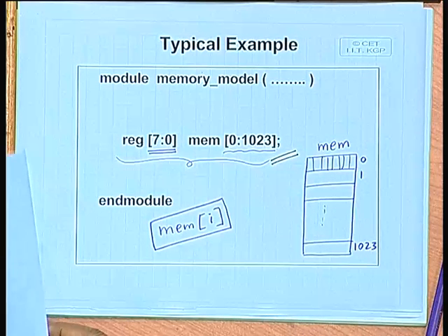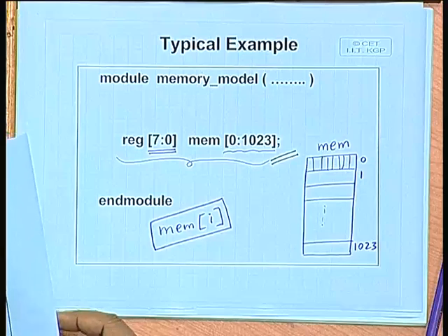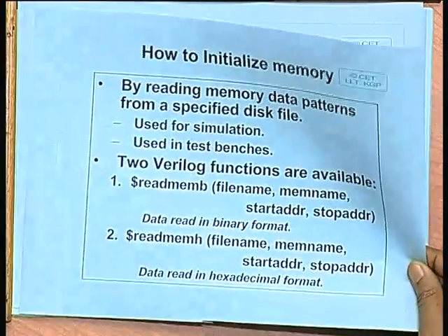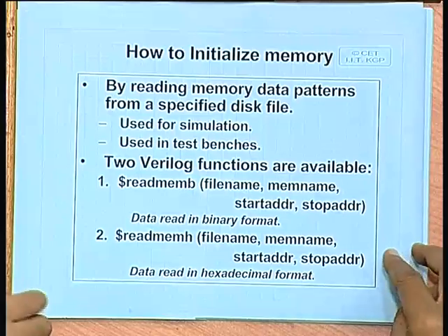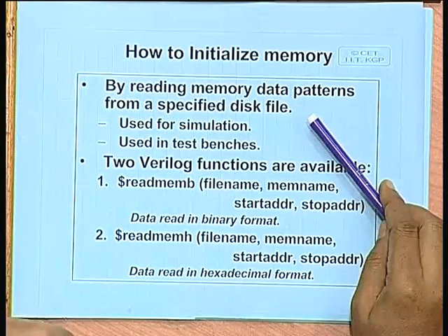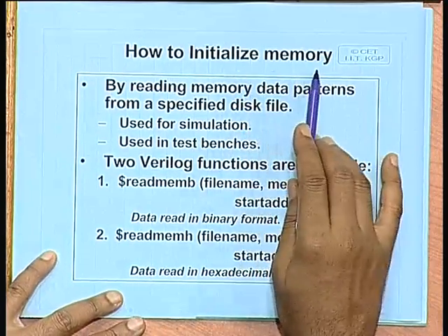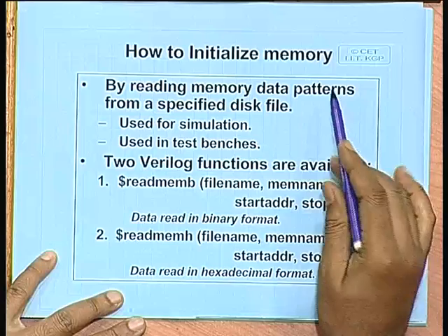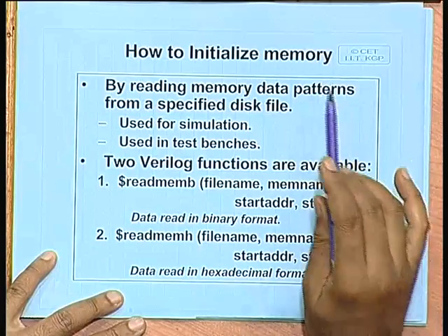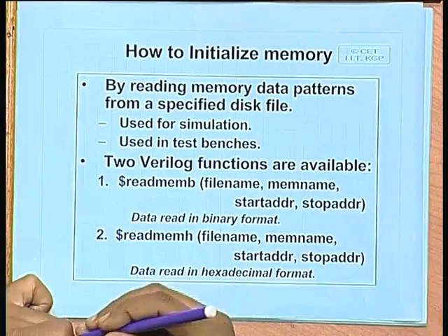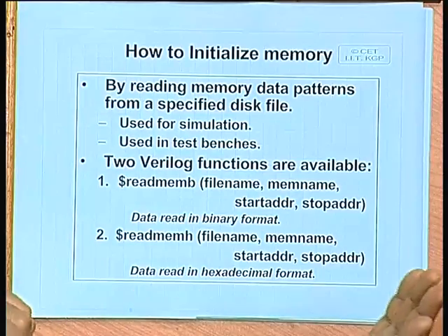So, next we shall see that once we have designed such a memory system, how we can initialize it. Initialization can go like this. See, this initializing memory, what we are talking here, this is from the point of view of simulation. Typically what happens in case of simulation is that you have a memory system which you have included in your design, and you have some data that you want to load into the memory system for the purpose of initialization.